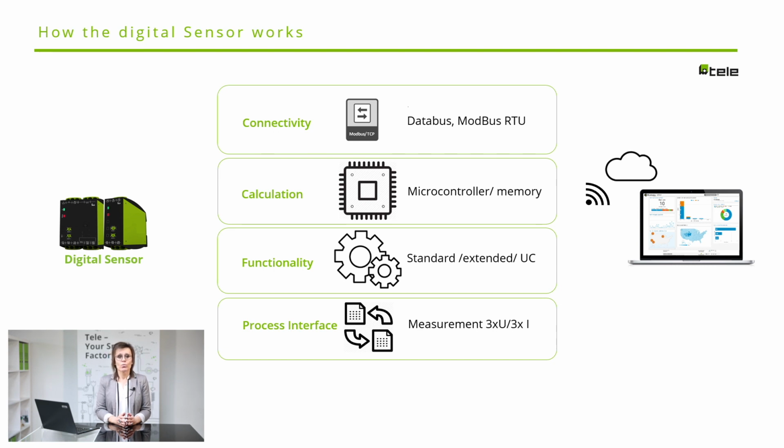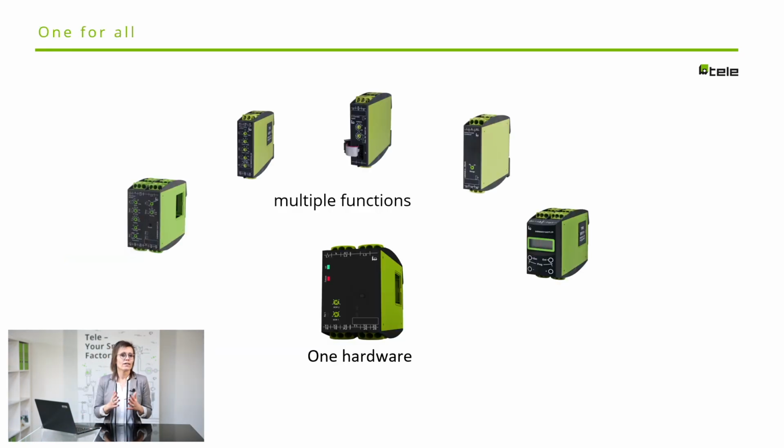Modern AI systems require this kind of high-resolution data to generate and analyze the processes. Due to the integrated functionality, ultimately it is more a data provider than just a sensor or sensing device. An advantage and USP of the digital sensor is that due to the local, fast and real-time reaction, any action which depends on set limits can be generated within the device, independent of the data bandwidth, update rate or availability of the network connection. This gives you an additional local actor device inside the same unit.